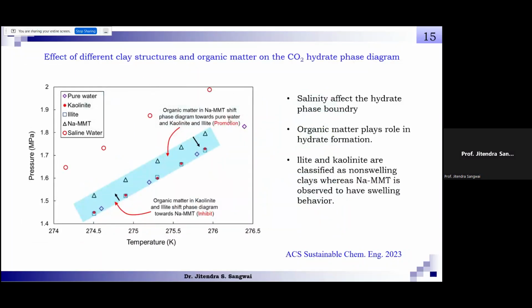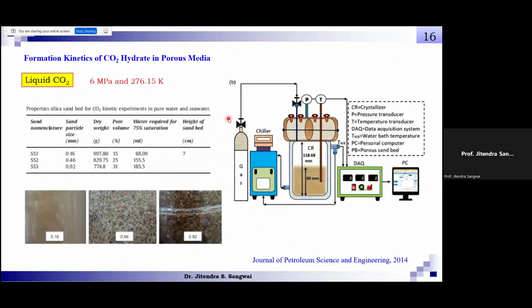Now, I'll just quickly run through some of the studies that we have done at the lab scale. We have looked at the impact of various sand particles to understand what will happen when forming hydrate from liquid CO2. We did experiments at 6 megapascal and 276 degrees Kelvin using a reactor, and we have a sand bed using different sand sizes.